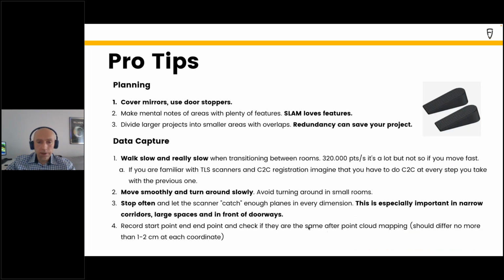Okay, now I would like to give you a few small but important tips about the scanning process. Firstly, consider useful small equipment, door stoppers, to prevent doors from closing during scanning, and you'd better have plenty of them. They are cheap and very, very useful. Painter's tape is used by me to stick checkerboards on walls.